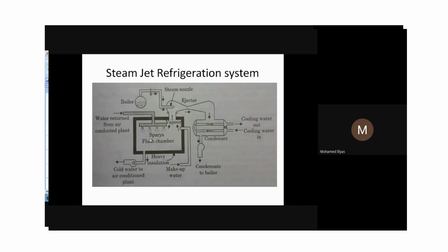So if we are ready to pay for more power consumption, then we can accept it. Q is the amount of heat extracted, m is the mass of the water, Cp is the specific heat, and DT is the difference in temperature. In this way, we can understand that every time we turn off refrigeration at around 5 to 6 degrees Celsius, that is the relation between turning off and the capacity of the refrigeration. I hope when the temperature is decreasing, the water temperature will decrease here.